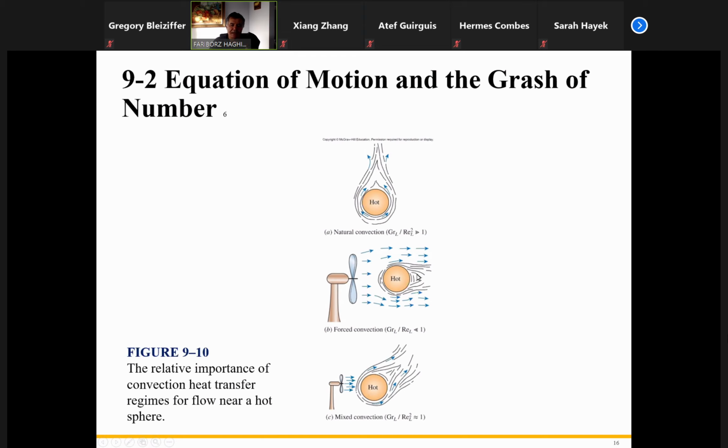If you look at here, the streamline is in parallel with the forced convection. It means natural convection has nothing to do with it. But if you look at here, it is influenced by the forced convection and also by natural convection going this direction, okay? Therefore, in some cases, we can only ignore forced convection. Some cases do this one. Therefore, we always have to calculate this number here and see if it falls in this range, or in this range. Okay? Any question, please?